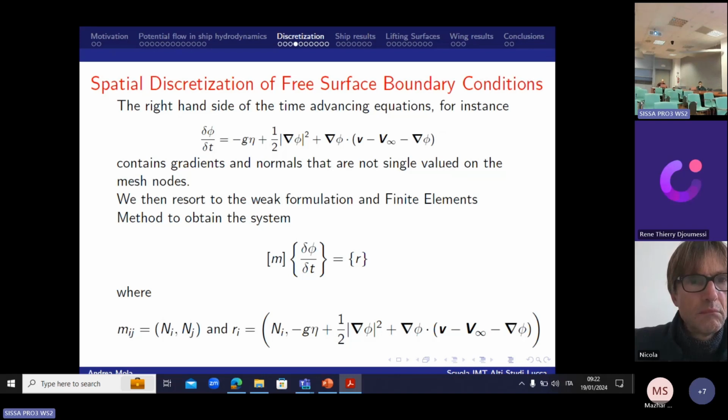which in this case we don't have. Another problem in the formulation is that when we want to evaluate this on the free surface, just to compute where the free surface nodes have to move, we have the gradient of phi, which is discontinuous at the nodes and between different cells. Again, basically, this has been obtained through finite differences on the free surface.